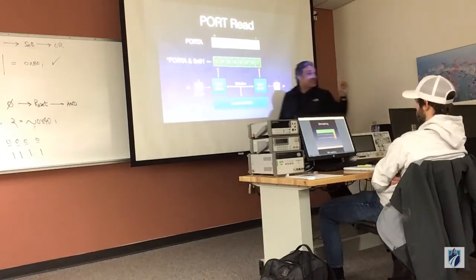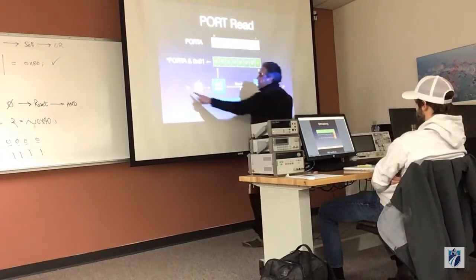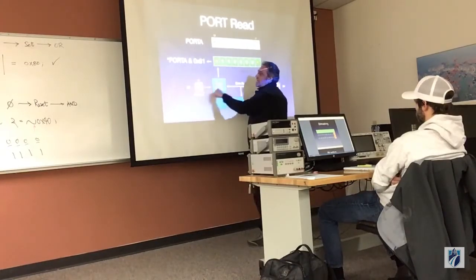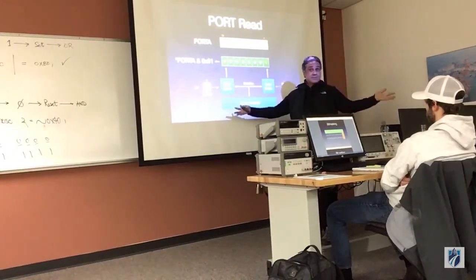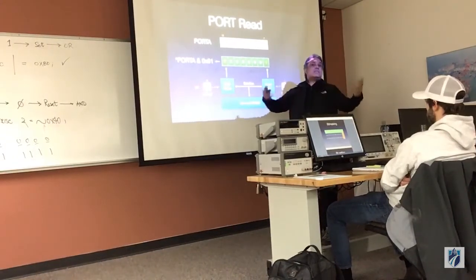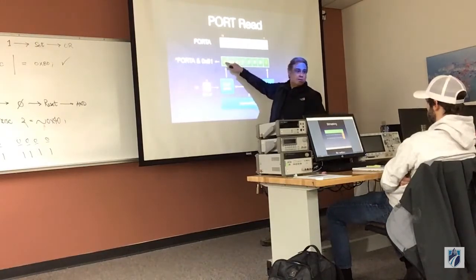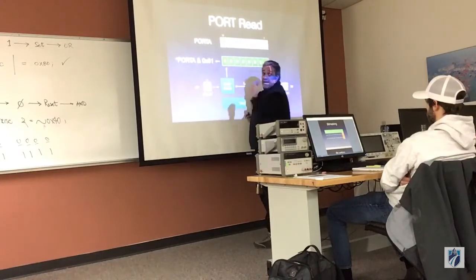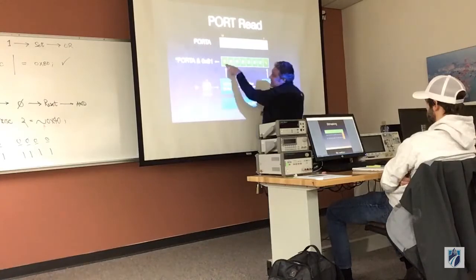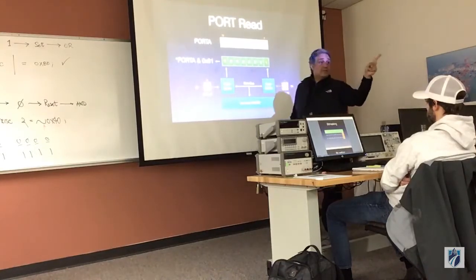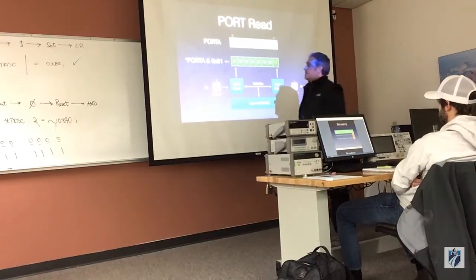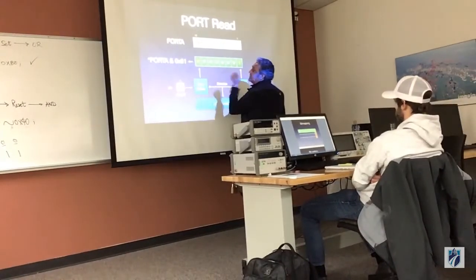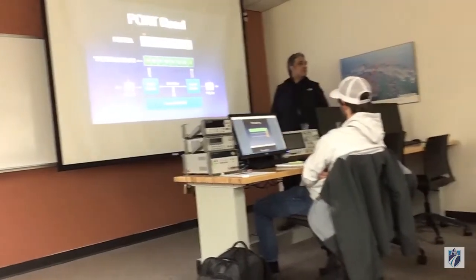And then, listen to what I'm going to say now, because this is very important. This behavior is not set up by you. In other words, this is going to happen because it is a circuit. There is no software that I need to do to pass the data all the way to the port. It will happen by itself. The moment that I make my tri-state, this guy, an input, you put 0 volts, and this guy will become a 0. And at any moment when you are ready, if this instruction coincides with this moment in time, I will see that 0 coming through my software.